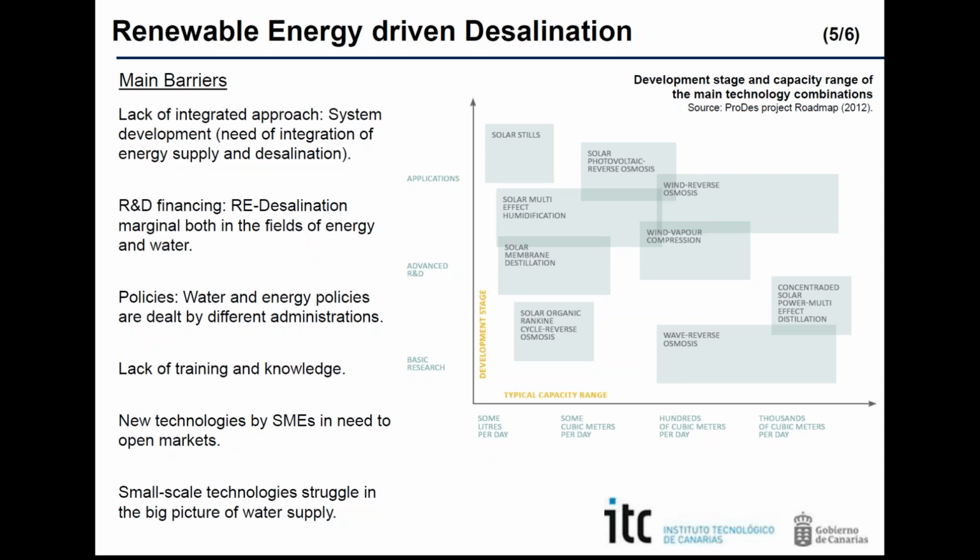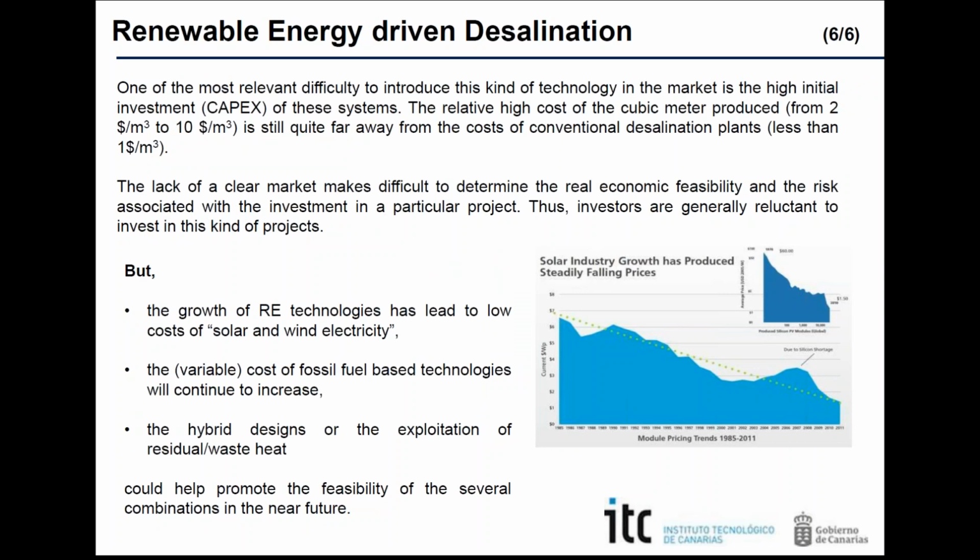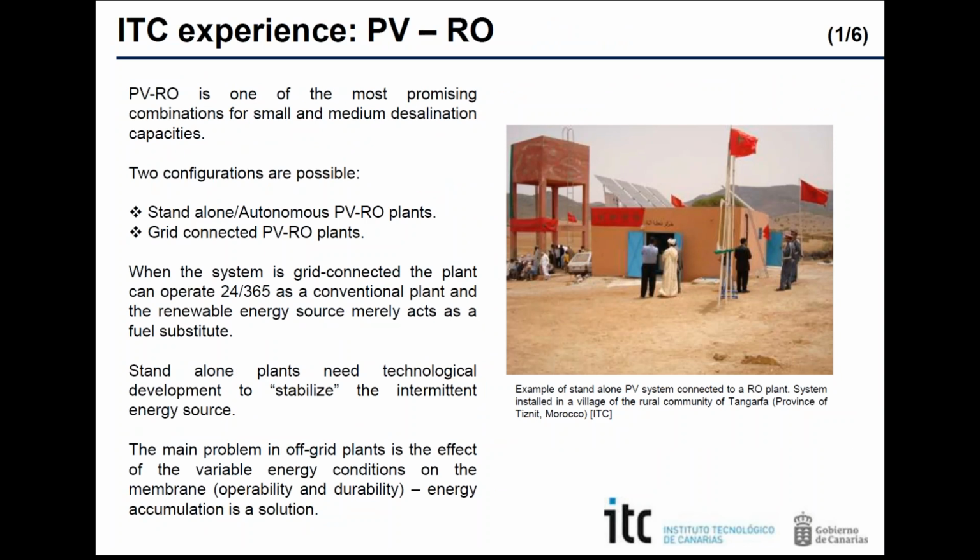Regarding energy, as I said before, energy consumption makes up to 60% of the total water cost. This is why we are here, sharing all this know-how with you. In the case of seawater reverse osmosis, it's now possible to have a specific energy consumption, measured in kilowatt hours per cubic meter as is done in this field, below 3. 15 years ago we had 15. Now we have below 3, sometimes even below 2. So it's a technology that is very efficient in energy.